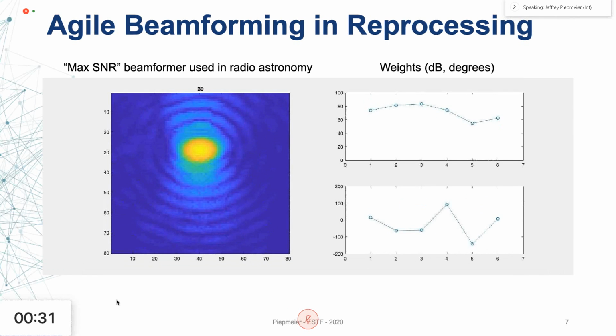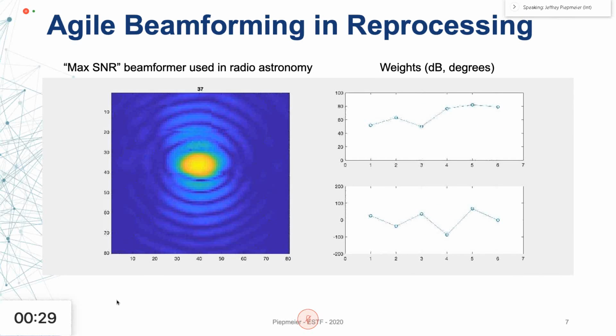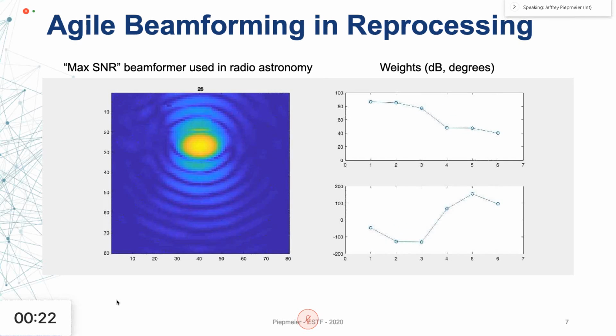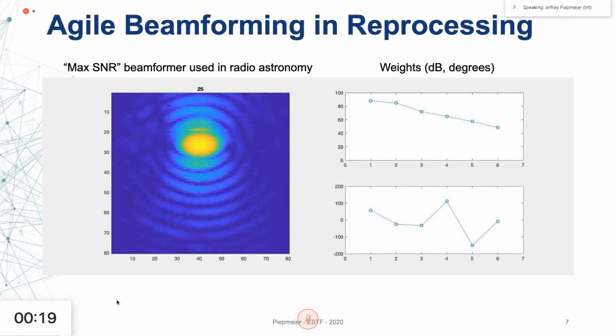We would probably use a different technique for Earth science, maximizing beam efficiency. But nonetheless, on the near field, on the compact range, we scanned the antenna patterns of all the individual elements, in 0.1-degree steps, to map out the half-degree main beam and recorded those IF signals. And in software, we just use the software correlator to compute the covariance matrix.